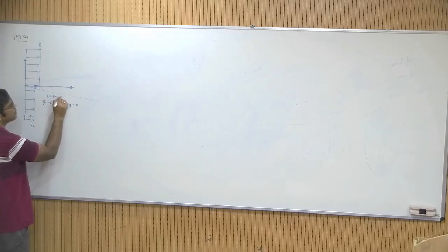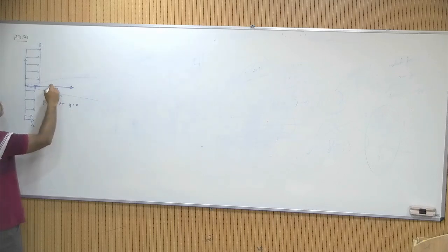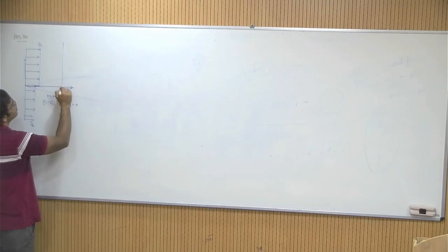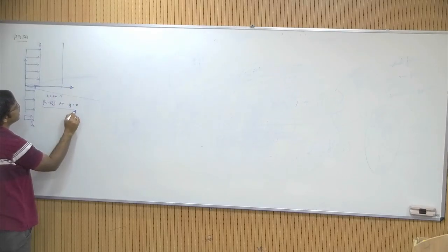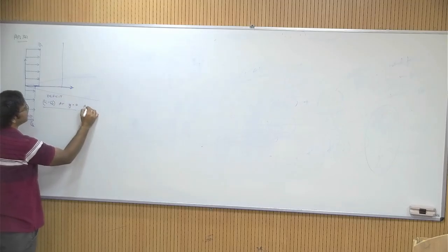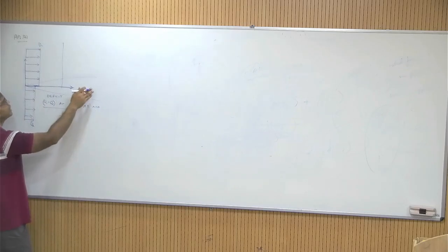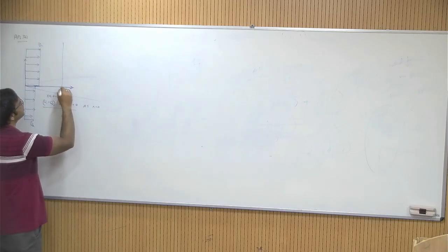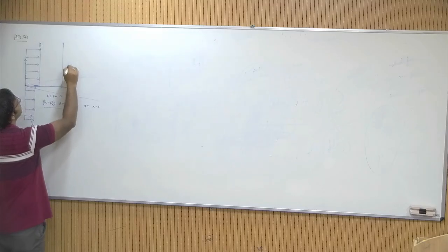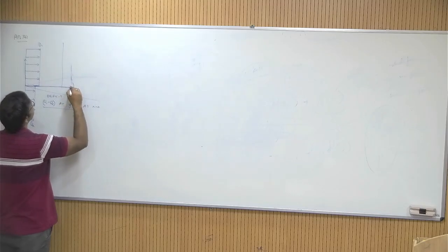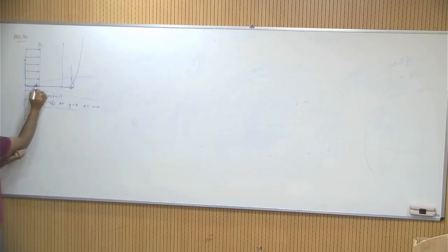So this velocity deficit at y equal to 0, this is what diffuses upwards. And of course the velocity deficit will not remain constant at y equal to 0. So this is at x equal to 0, and as you move ahead, the velocity deficit will change a little bit, and you see a diffusion of velocity, basically something like this. So you see that this profile as you move forward becomes smoother and smoother. So this is actually a case which is very similar to flat plates and not free jets,